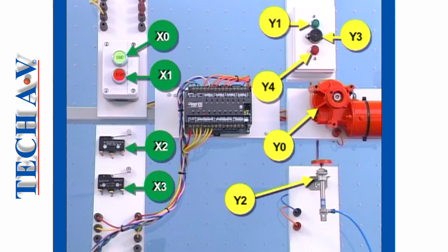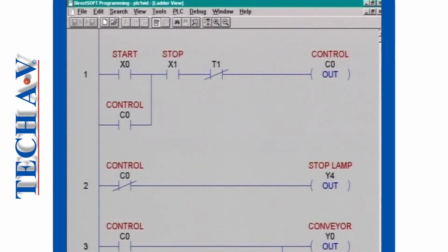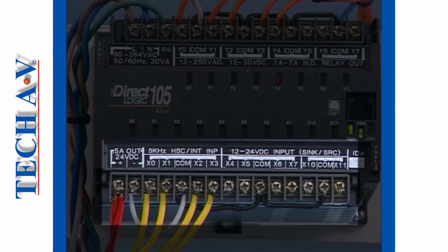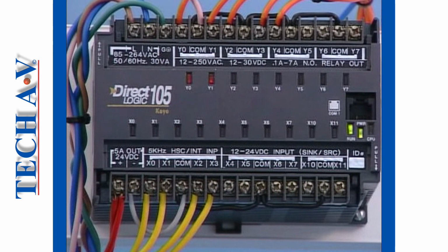Now you might appreciate why, when maintaining or tracing faults in a PLC-managed system, it is imperative to know what each external device is, where it is located, and how it is connected, which is why the use of relay symbolism is such an important part of the system documentation. But as far as the PLC is concerned, it does not need to know what type of input or output device is being used, only the address location of each device and what must be done with the on-off signals appearing at the input points.